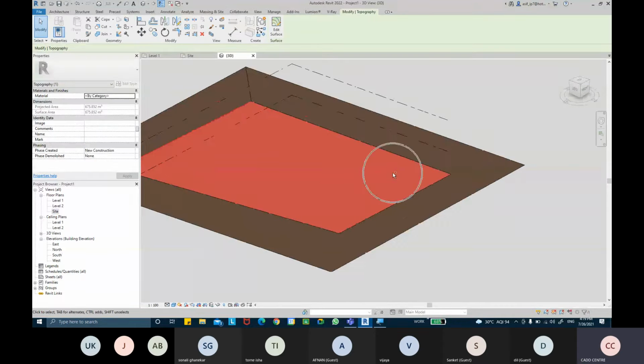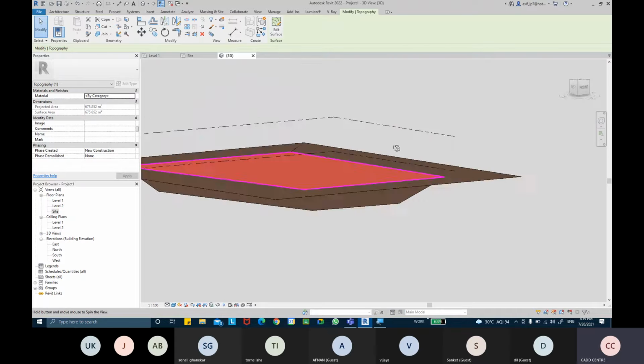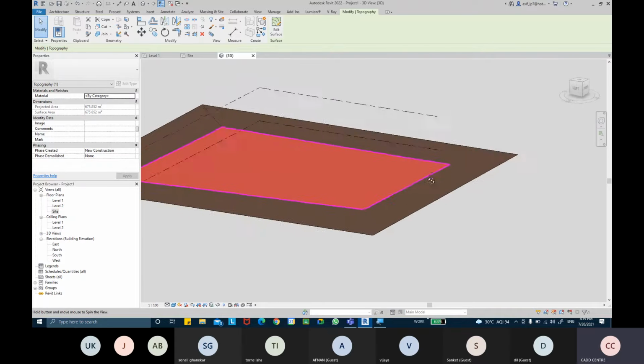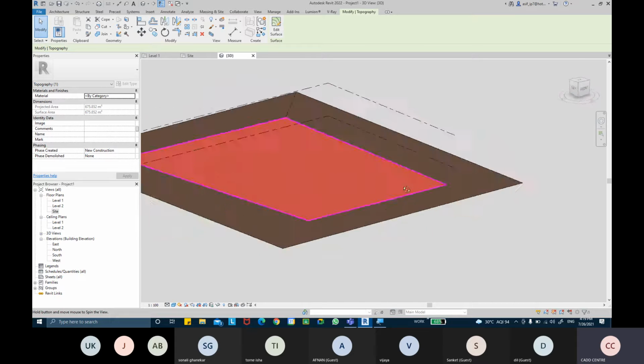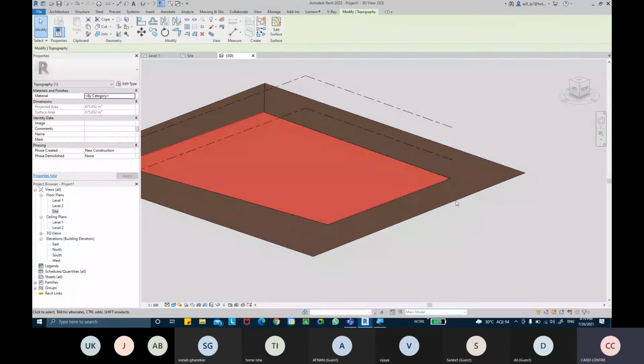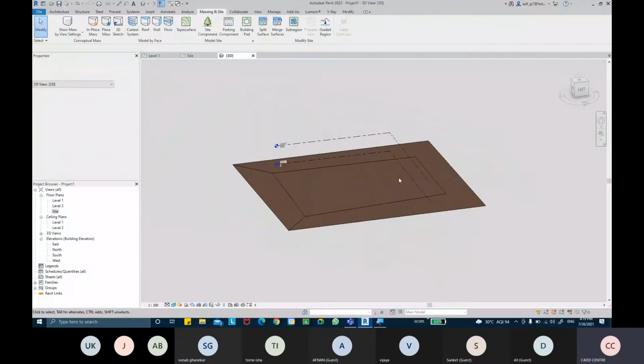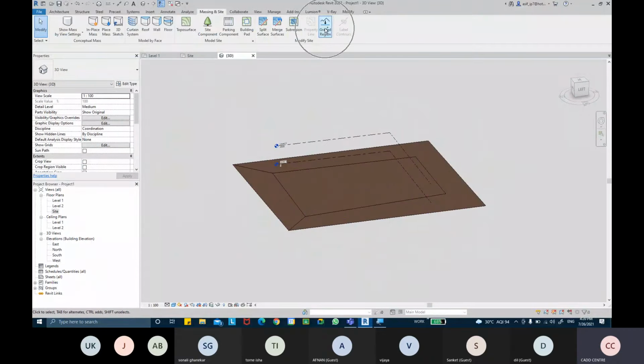Okay, so if I select this surface, it will tell me what was the projected area and how much surface I have to cover to fill that excavation work basically there. Okay, so that's the excavation surface area, and that's the projected area, which are both similar kind. Okay, so that's perfectly done. So we got that filled up. You can level your topo surface by using the graded region.